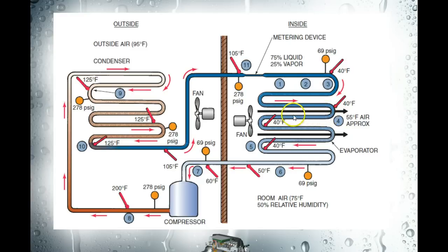So the refrigerant continues down through the coil. It's boiling, boiling, boiling, changing state from liquid to vapor. And the coil is designed so that near the end of the coil, all the refrigerant is boiled off before it leaves the coil. At that point we're starting to pick up superheat, and we drop off the pressure temperature chart that we looked at earlier. Now we have just refrigerant in the vapor state, and so it can't change state anymore. So any heat that's added to this is called sensible heat.